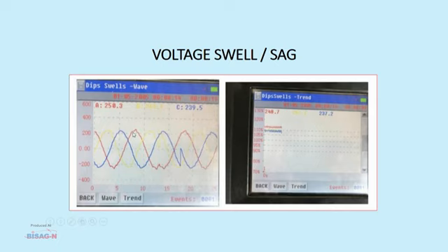This again emphasizes that there is slight variation in the sinusoidal waveform. That means there are certain harmonics injected into the system, for which we have already taken the measurements. This can be corrected. Hence, from the figure we can visualize that we have to put certain power quality equipment in place. This slide shows the dips and swells in the system.